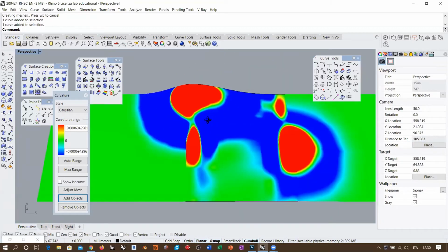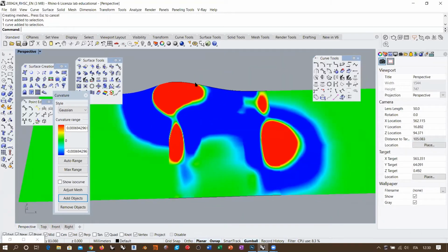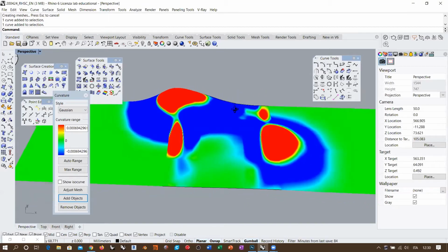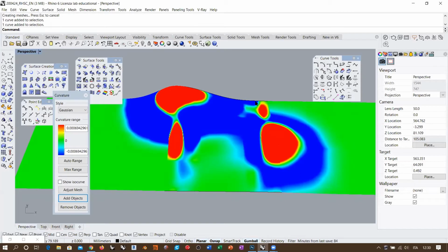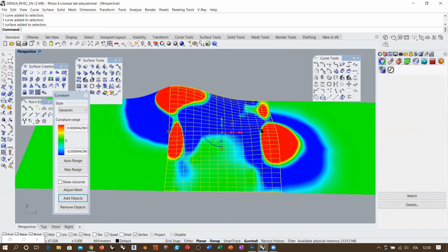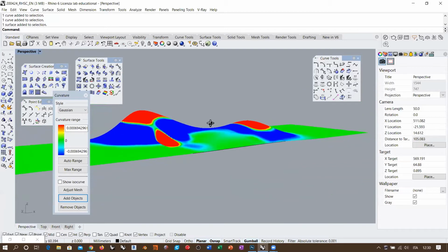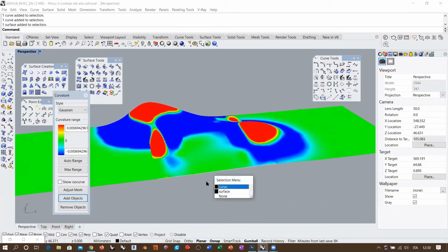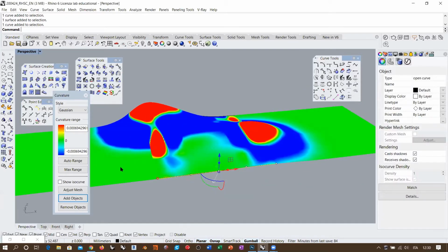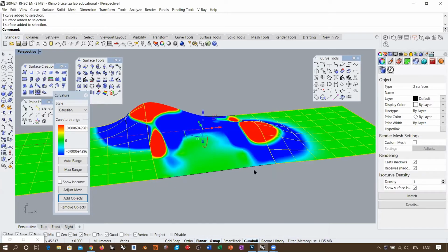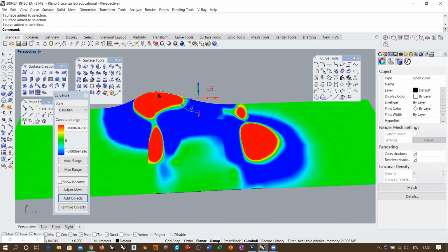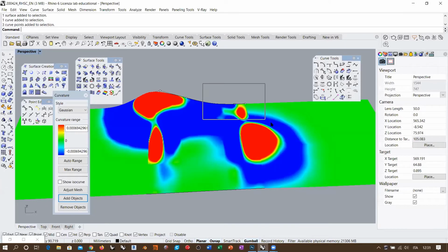So in this case, we are considering all the surface edges and cross sections as having the same importance. Moreover, the command allows you to select curve continuity, geometric continuity along the surface edges. So this would be the best solution in this case. Of course, you have to adjust the continuity between this curve and the adjacent surfaces, not taking tangency, tangency, like we did here. Okay, we adjusted to curvature, curvature.